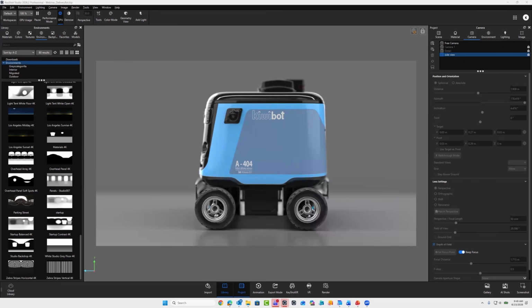Could you talk a little more about translucent materials and how their size affects the way they look? Yeah, okay. I can't really show it on this because this model's prepped, but basically, if you are working with translucent or transparent materials, scale is going to affect how your light passes through. You can make adjustments to your transparency distance so that it is a little bit more transparent and light passes through better.